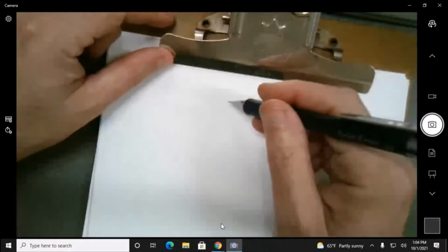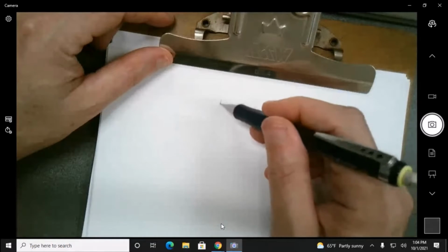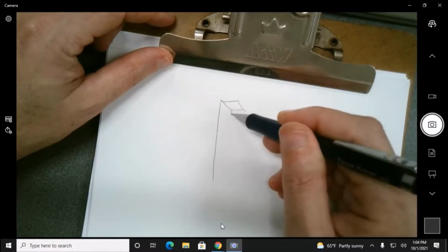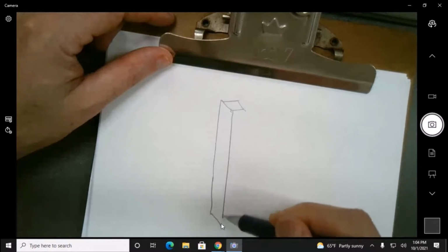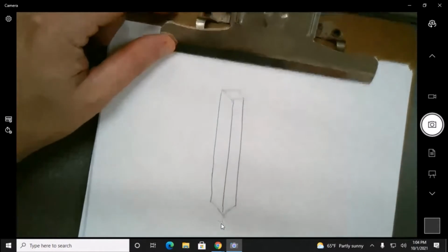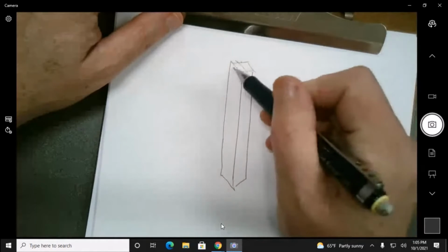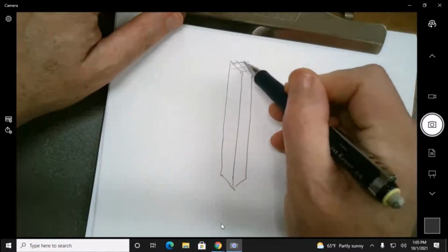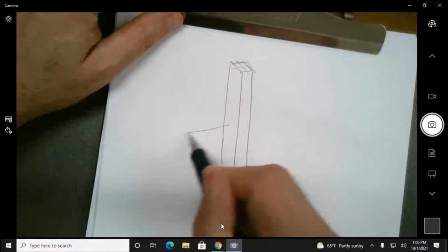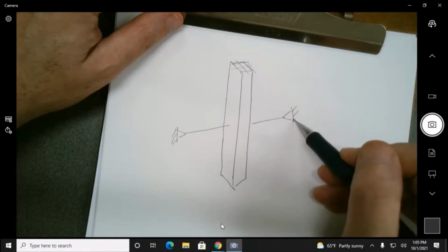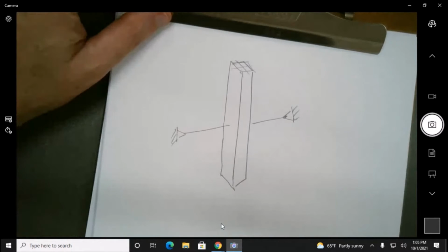One of my answers is pretty close. I have attempted to make a problem before where I had, I'm just going to draw it like a rectangle here. I guess I maybe should have made it look weaker on one, and I alluded to this in class, where this is going to be the weak axis right here, if I had drawn it a little bit narrower. And I've had it before where I put a cable right in there, so you can't tell which one's the weak axis. So there's 1 column and 2 potential different failure modes.